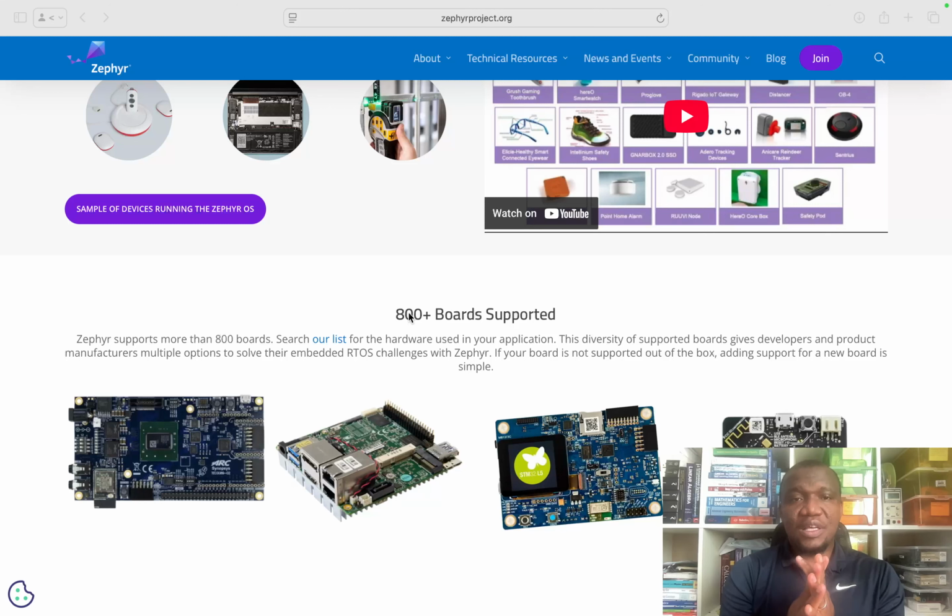So let me give you a concrete example. Let's say you write code in Zephyr and your target is for an Atmega. What's essentially going to happen is you write using their public APIs, and then you tell the build tool that you want to compile this firmware for Atmega. And it is the work of the tool chain, the build system, to look for the appropriate tool chain.